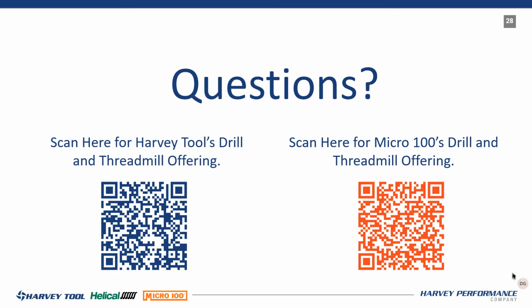Well, here's the thing. We have deep drilling options, and when you say deep drilling, I'm going 12 times D and over. We go to 20 times D on our coolant through drills. Will those work in copper? Yes. Are they designed for copper? No. Can we get them to work? Yes. So we do have choices for copper for deep hole. Depending on how deep you're going, I would evaluate that process and see if it's the right application.